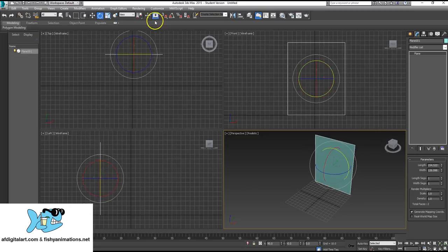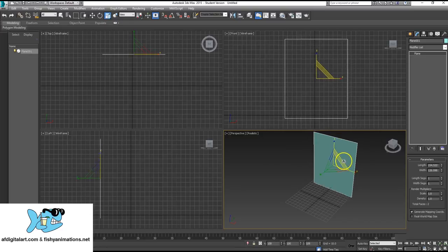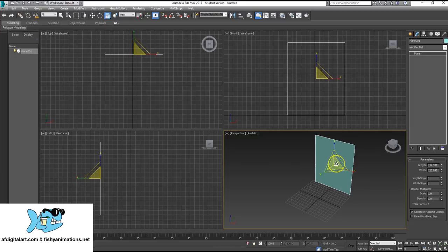Now what I can do is I can also even take the Scale tool, and if you notice, I want to left click and drag on the Scale tool from the middle, not the outside. Notice that this actually will create non-uniform scale. This is actually creating a warp effect, and that's going to really lead to a lot of terrible results in the end. It's called deformation. We don't want to do that, because if you create a shape with non-uniform scale using these other types of scale tools, and this was a character object that would become rigged later, and we use the animation rigging or bone tools, it's going to create a lot of warping and distortion.